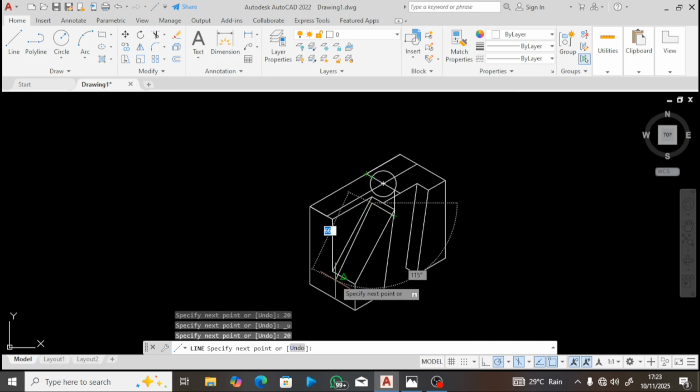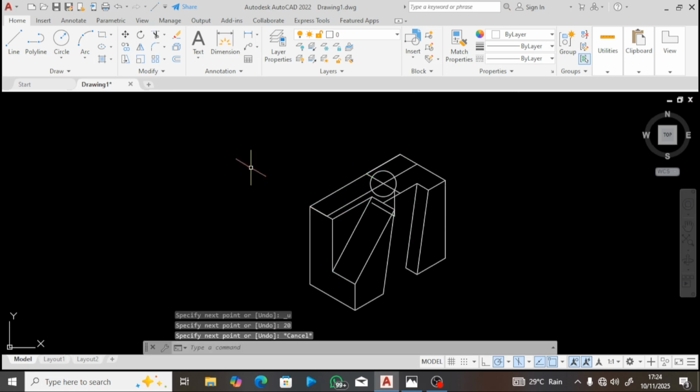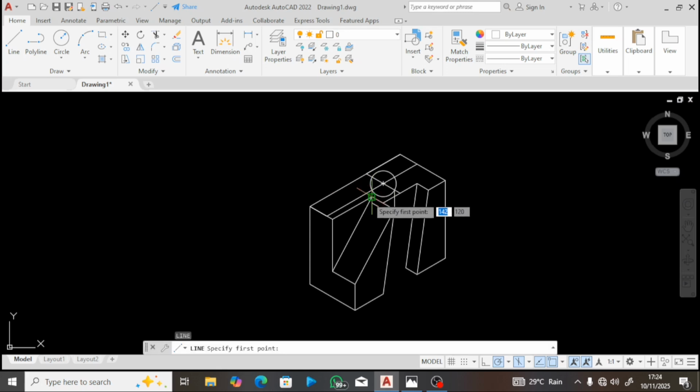But before I do that, let me show you something. Now you can see that I want to form an isometric square. The size must be 20 because the diameter is 20. So I've come like this 20, like this 20. So I will need to come like this 20 to form it. So it will now form something like this. Then I'll be able to draw this circle. So pick the last command, click enter. So come here. You can see that it has already shown green. So join it with this. Yes, you see that it's already 20 now.